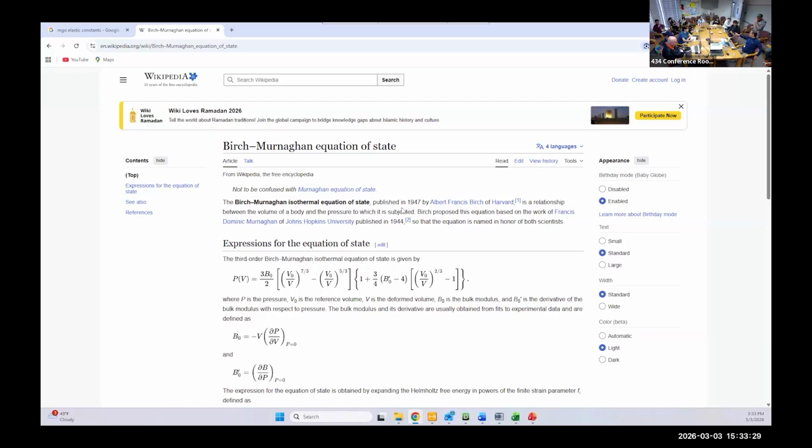So basically, the first approximation is you take the product of thermal expansion and bulk modulus. That's approximately the thermal pressure for a given temperature. So you calculate alpha at a certain T, times the bulk modulus K, times the delta T, and that gives you the thermal pressure. Approximately. The question is, the bulk modulus is also a function of temperature. Yes, it is. That's why you're doing it this way, where you're referencing everything to ambient conditions.